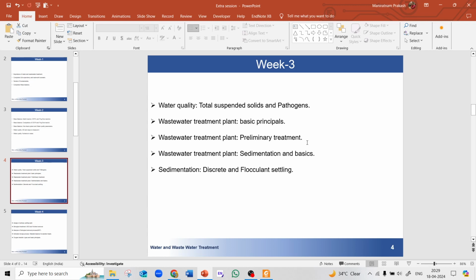And finally advanced treatment. Generally after secondary treatment people discharge their water, because after secondary treatment most of the parameters written in CPCB are fulfilled. Now suppose at some place they want to treat their wastewater in such a way that they can drink it, meaning that water can be potable. Then there comes another treatment unit, the advanced treatment unit. I don't remember where this practice is being done, but there are several places where there is one extra treatment unit.